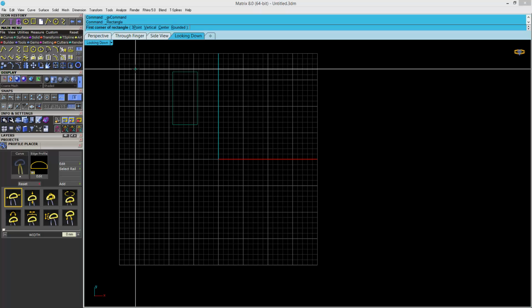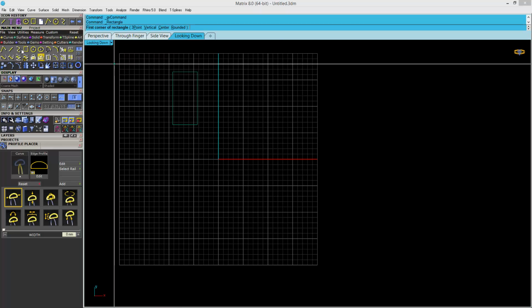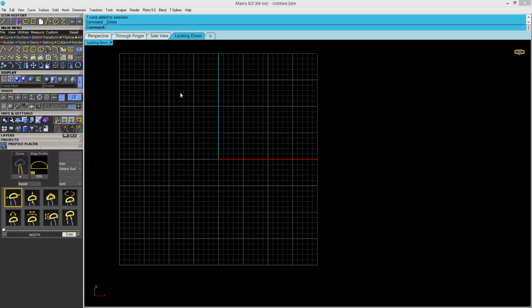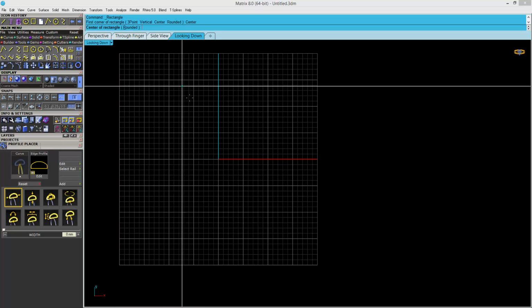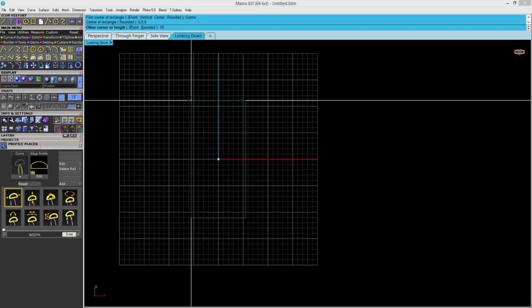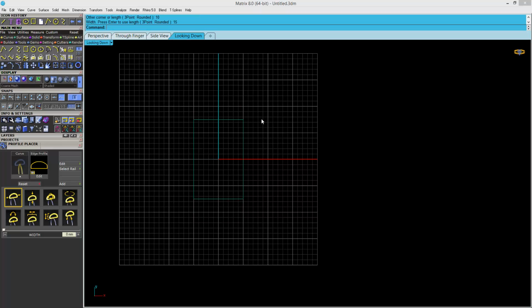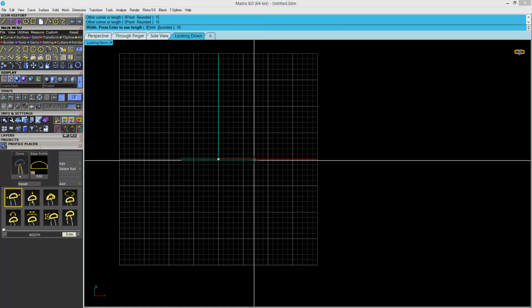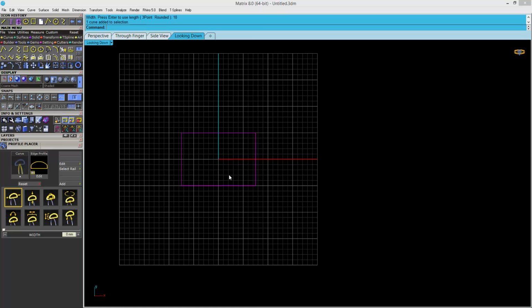I'll show you the important options over here. If I need the rectangle on center, I select this and then I press center, then I press F4 and then I give a dimension like 10 millimeter or 15 millimeter. So this is 10 here and 15 over here. Or if you need the reverse, you press 15 first and then 10. Agree? Now, not based on this option, but I will give you some work once you are used to these commands.